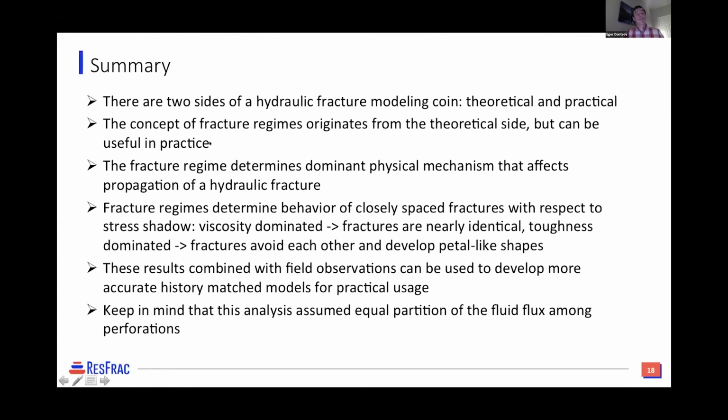But I wanted to give you in this talk the concept of fracture regimes, because the regime determines the dominant physics which affects the fracture geometry. And I hope I convinced you that for the case of multiple fractures it's important, because in the viscosity regime you have nearly identical fractures. They don't like to interact, so viscosity kills it all. But if toughness dominates, on the other hand, then they really don't like each other, they really want to avoid each other. And again, just keep in mind all the assumptions made in the analysis, like uniform partition of flux, no layers, and so on.